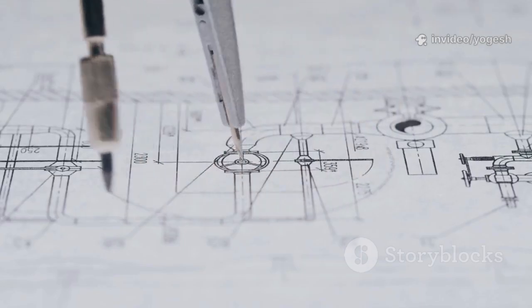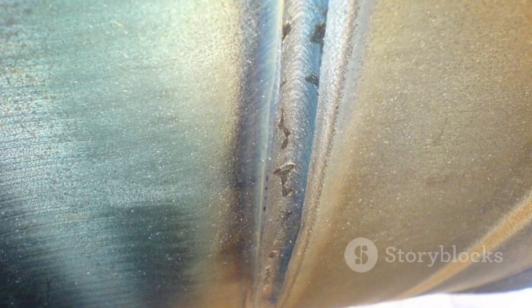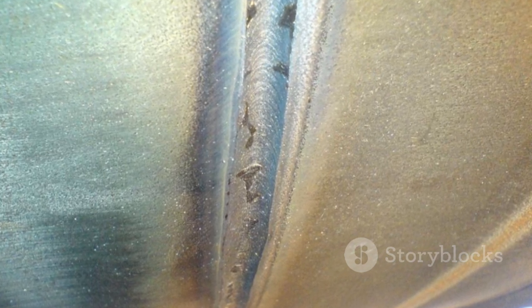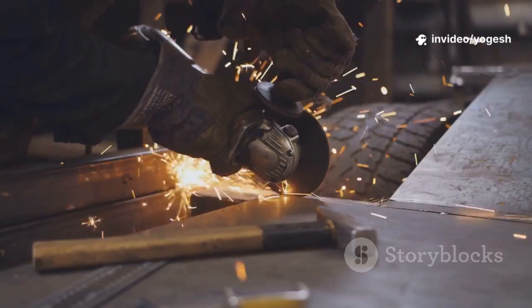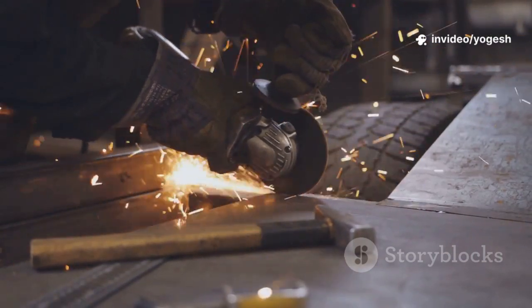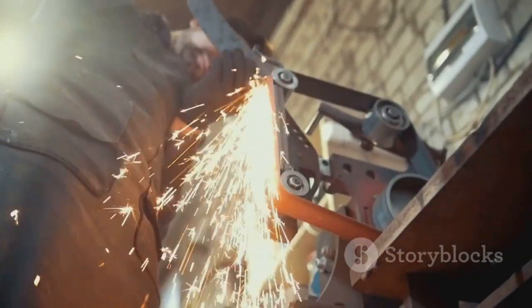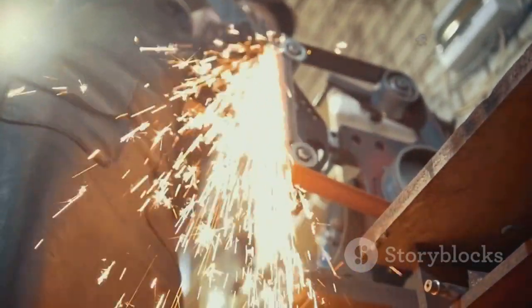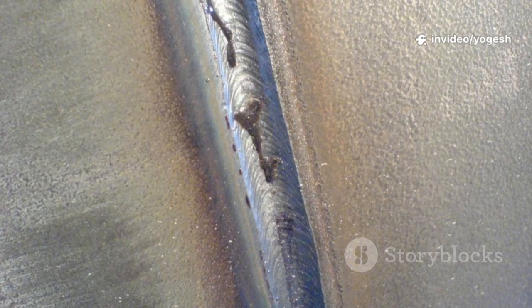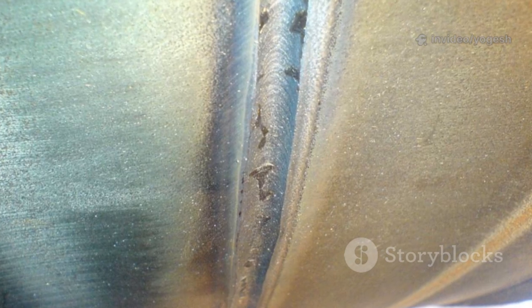Staggered or aligned patterns are shown by offsetting or aligning symbols on the reference line. Contour symbols indicate the final weld shape: flat, convex, or concave. Finish symbols specify methods like grinding or machining for smoothness or aesthetics. For example, a flat contour with a G finish means the weld must be ground flush. These symbols control both the strength and appearance of the weldment. They ensure the finished product meets all design requirements.